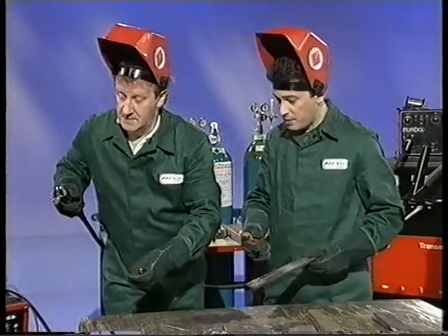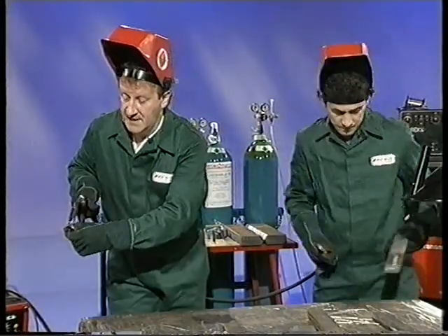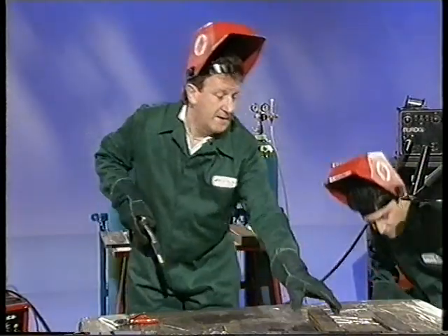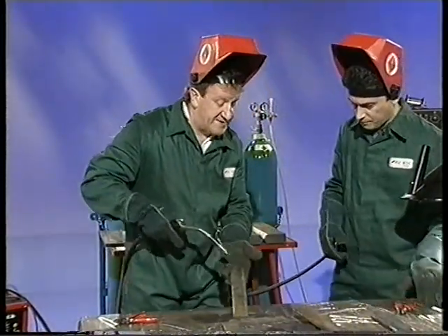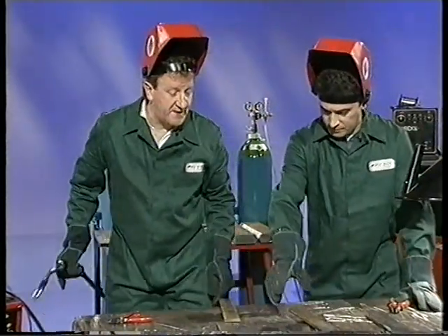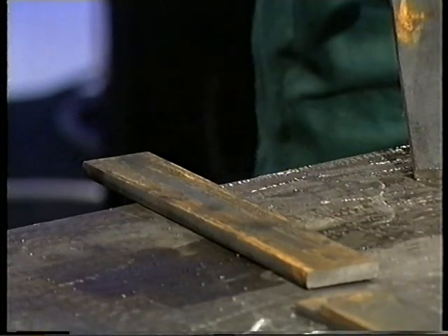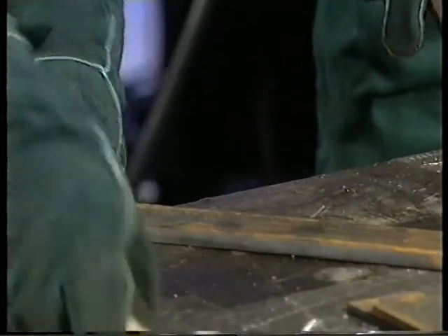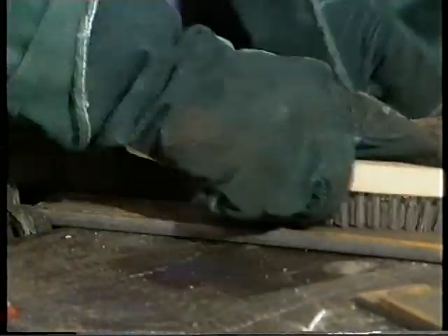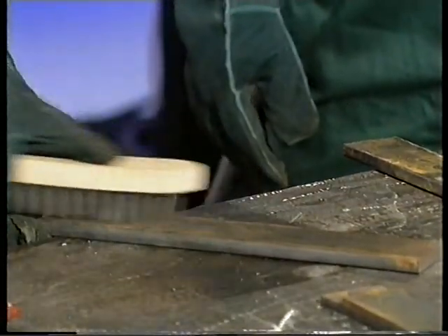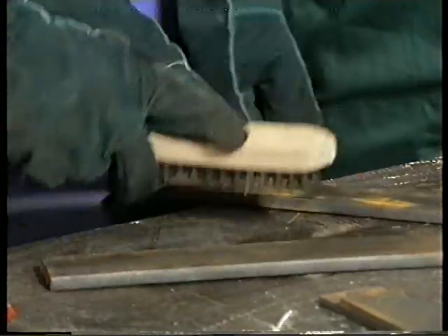Smashing. Okay. Shall we go on to welding some joints next? Yeah, let's try a fillet weld. As I said before, there's mill scale and some oxide on this surface. It's probably advisable just to give that a light wire brush, just to get rid of anything that's loose on the surface. But still repeating that if you wanted very best results, we would grind back to clean material.